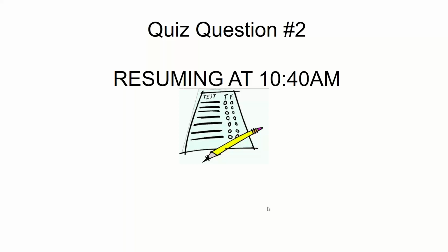All right, we did have a question come in. What MERV rating would you recommend if your house has a 1-inch or 4-inch filter size and your wife and kids have allergies? The 1 versus 4-inch, we're going to address that right now and give you some options. But as far as the MERV rating, just to be clear, the MERV rating can be independent of the depth of the filter. Sometimes they're related, but it doesn't have to be.